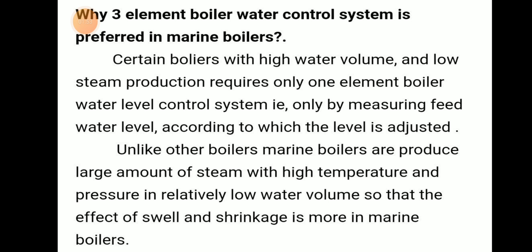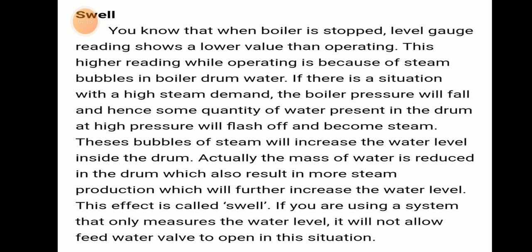Normally, certain boilers have high water volume and low steam production, so for that type of boiler only one element water level control is required, because the level can be adjusted just by measuring the feed water level. But marine boilers produce a large amount of steam with high temperature and pressure and relatively low water volume, so swelling and shrinkage is more in marine boilers.